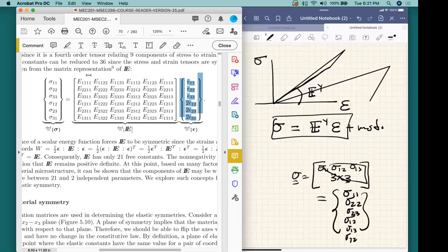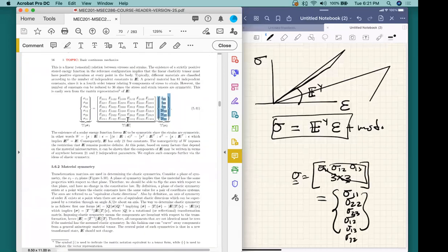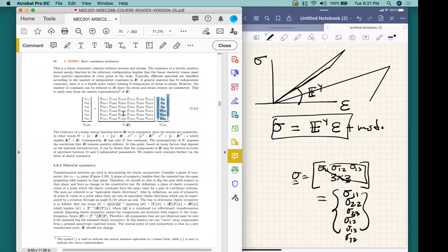And it turns out this matrix comes to the rescue, and that is the so-called elasticity tensor. In 1D, it collapses back to our friend Hooke's law. But in 3D, it's a big mess. So even in the linear case, where it's a linear relationship between a quantity called the strain and a quantity called the stress, it has a lot of constants in it that have to be benchmarked and understood.